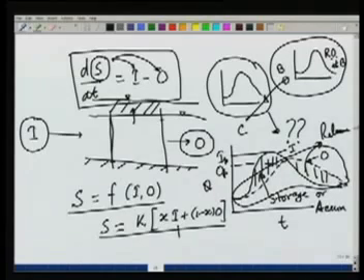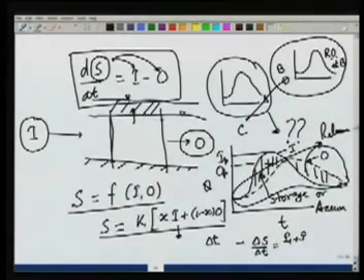This is called the Muskingum equation, and when we route the flow through the channel, what we do is we take small time steps, let's say delta t. We assume some inflow to be average during the time delta t, and then we write delta S over delta t equals average of I1 plus I2 minus average of O1 and O2.